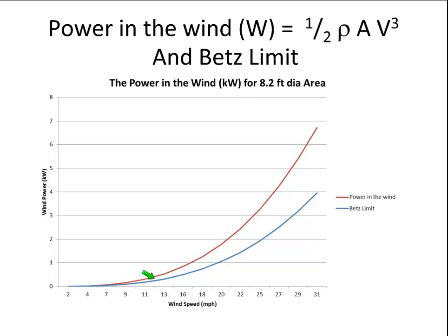So again, if I'm looking at that wind turbine, remember that 1 kilowatt rating, I said 17 miles an hour. Well, I can't catch that much. So now the reality is it's got to be in this range where it's got to be maybe closer to 20 miles an hour. And when we show you how much it can catch, which I have those numbers following up, that number is going to be out here. So its rating is on a very, very fast wind. And so the reality is that's why we're starting to rate these turbines differently as far as having a rating.